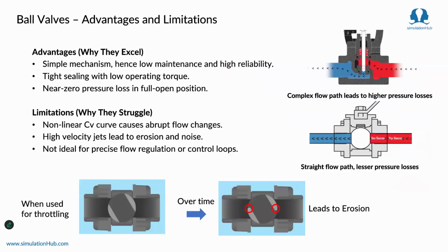So moving to the topic at hand, it's related to ball valves and V-port ball valves. I'll list out the advantages of ball valves. Why do we care about ball valves so much? Ball valves, again, as I've mentioned, have a very simple mechanism. It's a quarter-turn valve as compared to a globe valve, which is a multi-turn valve. If it's manually operated, you have to turn it a lot to get that linear actuation. In the case of ball valves, it's a quarter-turn valve.